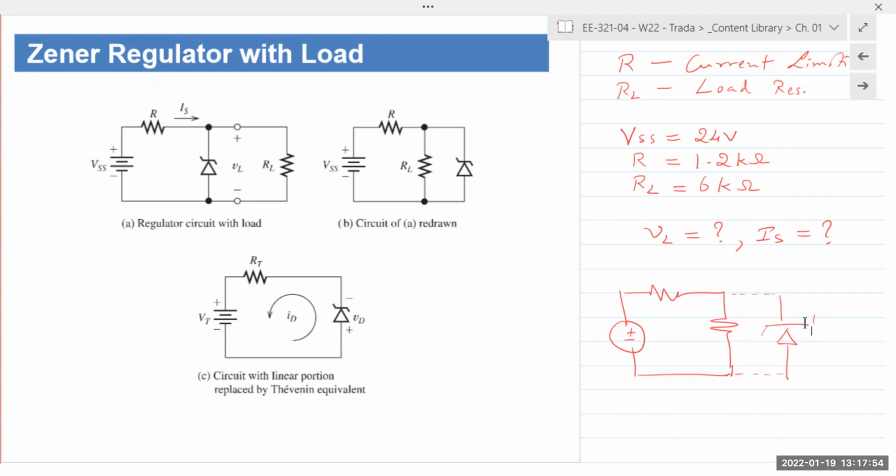So the voltage that is being applied is not the same as VSS. We need to find that voltage. And that voltage is given by the Thevenin equivalent network, or Thevenin equivalent circuit. For this particular circuit, it is as simple as just applying voltage division. Other circuits, it will be something else. But for this circuit, it's simply voltage division.